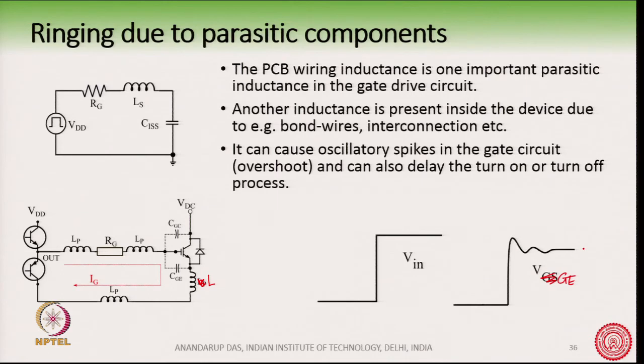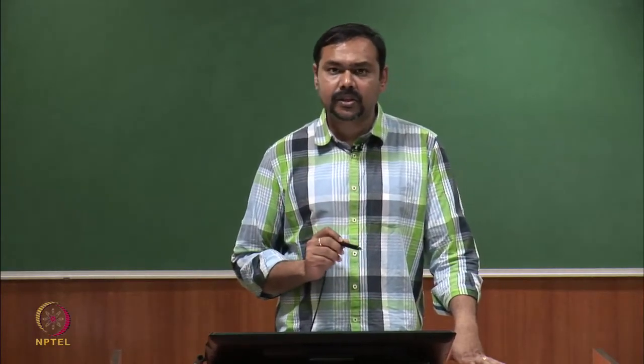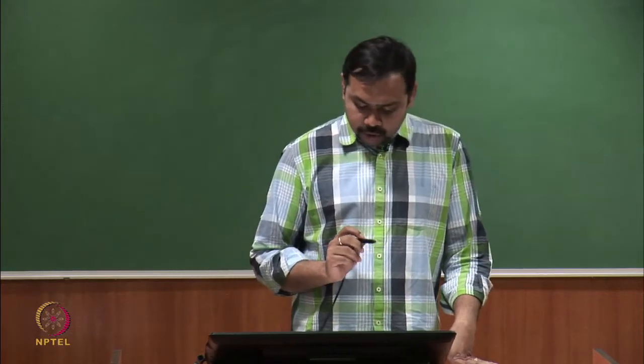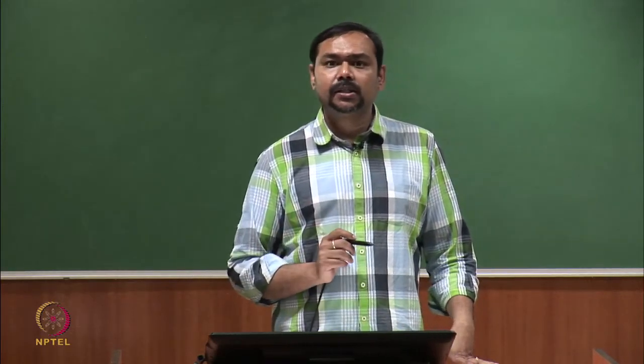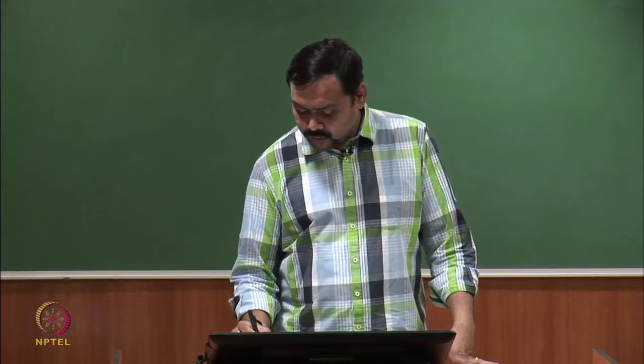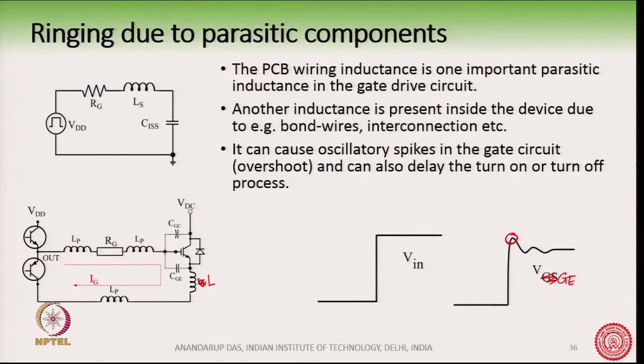This is because of the parasitic inductances in the circuit, but it must be kept in mind. So, what is the effect of this? Not only will there be a peak, but this can also delay the turn on process of the device. So, these are the important effects of this inductance.